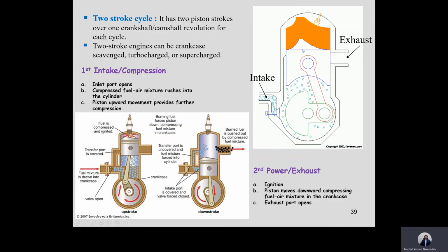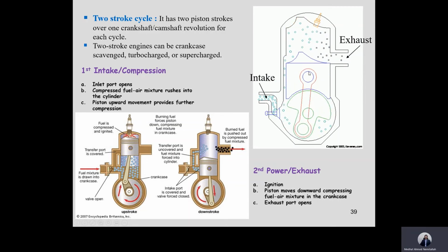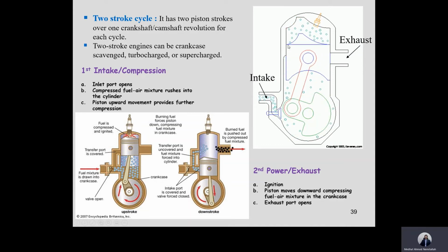Also, in the two-stroke engine, air plus fuel is introduced beside the piston. And on the piston's side, we should have a lubricating oil ring, and all of that. So the oil should be dropping here. But inside the crankcase, we have air plus fuel. That means some oil will get inside the cylinder and it will be burned. And it will result in an excess amount of emissions.